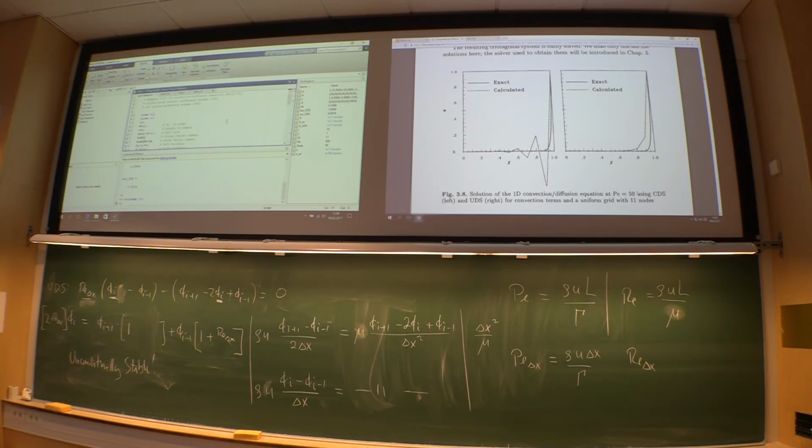Okay, if we now go back to the one we had here, jumping up and down a little bit, how can we get the central scheme to be stable? Because the central definitely is more accurate, but we can't have this up and down motion. Well, actually, there's only one remedy. Use more cells. You have to resolve the spatial resolution. So now I double the number of cells.